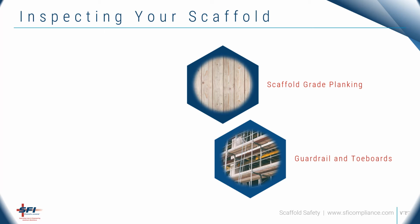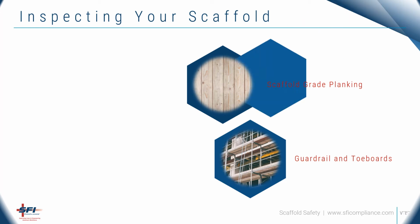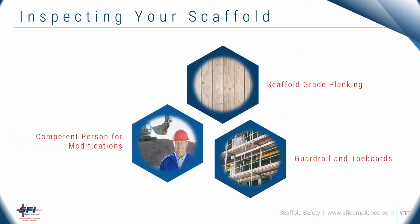The federal OSHA standard for construction requires guardrails when a platform is 10 feet or higher, but that may vary by state. The top rail should be about 42 inches above the scaffold walking surface, with the mid-rail at about 21 inches. It should be noted that the railings must be of adequate strength to restrain someone who has started to fall. Finally, never make any changes to the scaffolding yourself. Only designated competent persons can authorize modifications.